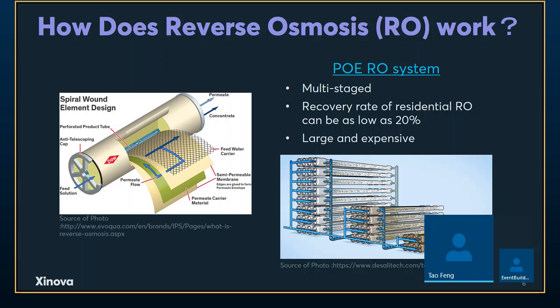The water collected after permeation of this membrane is the purified product stream, while the retained fluid contains a high concentration of contaminants in the reject stream. And the amount of this reject stream actually can be rather large.